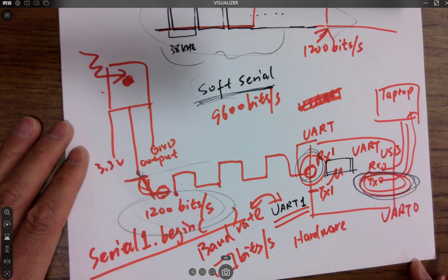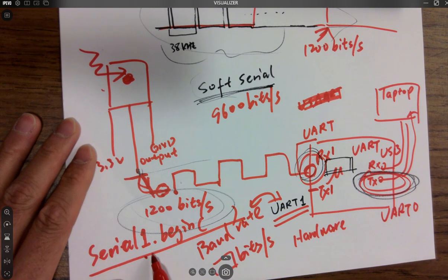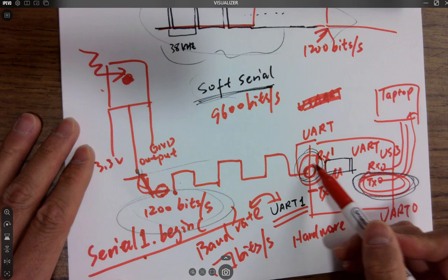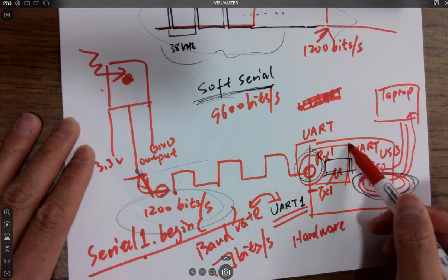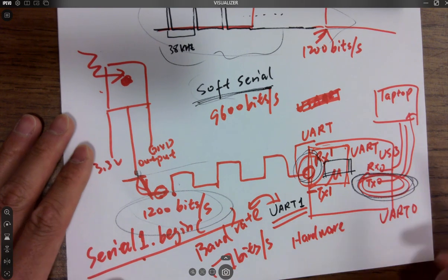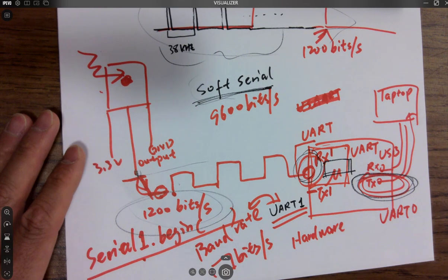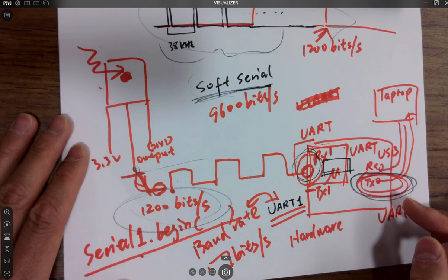Okay? And this function will modify the baud rate of your UART1 module, the digital module here, and there's a register that controls the baud rate, like other registers we have been using for the PWM, for the timers. It's a very similar thing, right? It's a register.